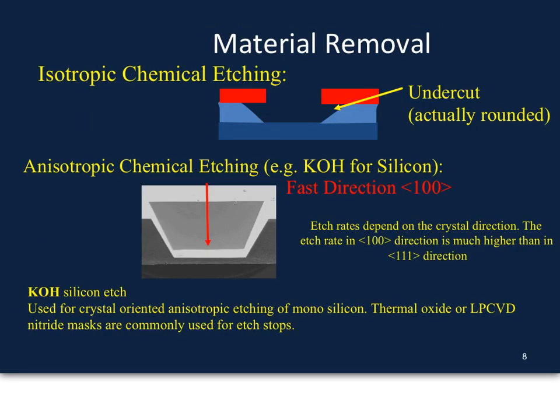We also talked about once you've got your patterned photoresist on top of your material, you need to get rid of it, right? So you do that by what's called etching usually, and so we have illustrated here isotropic etching versus anisotropic etching. For example, in an isotropic etching, you'd actually get these rounded cuts underneath. If you have the chemical etch degrading uniformly in each direction, then you'll have some undercut underneath the photoresist that